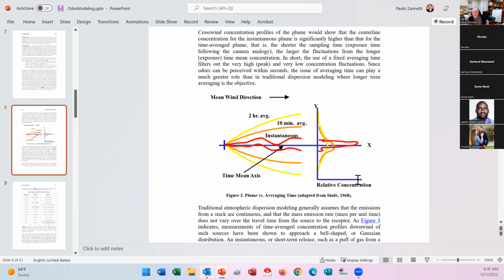So it's another challenge. I cannot use a model that simulates only hourly concentration like AERMOD, or if I simulate hourly concentration, I need an algorithm that tells me if I simulated 100 ppb over 1 hour, what will be the maximum during that hour? The maximum instantaneous concentration. Because odor studies require the evaluation of the maximum instantaneous concentration that could have caused an odor.